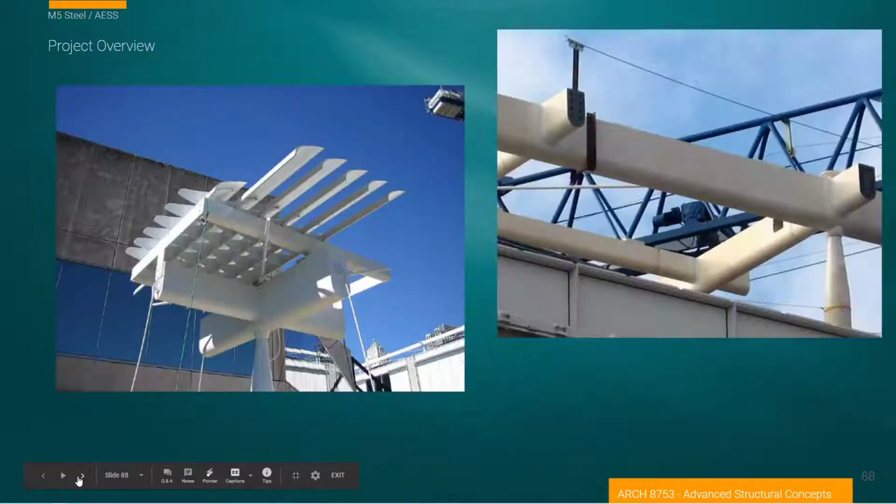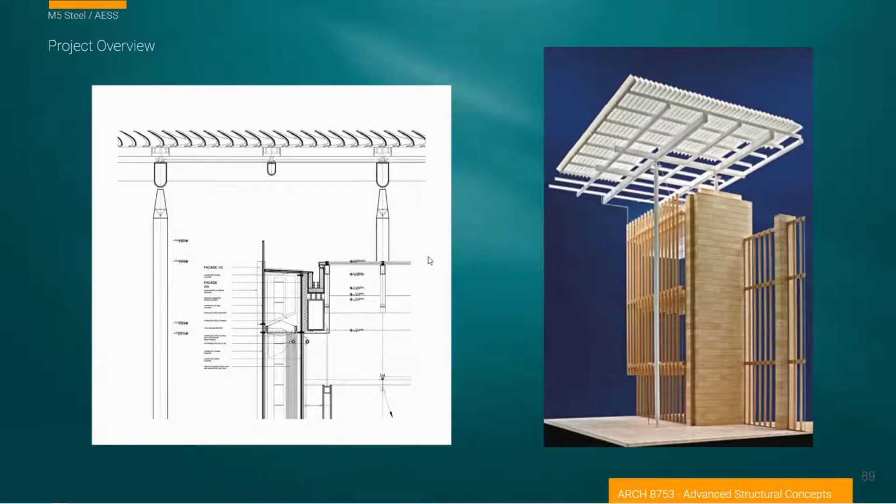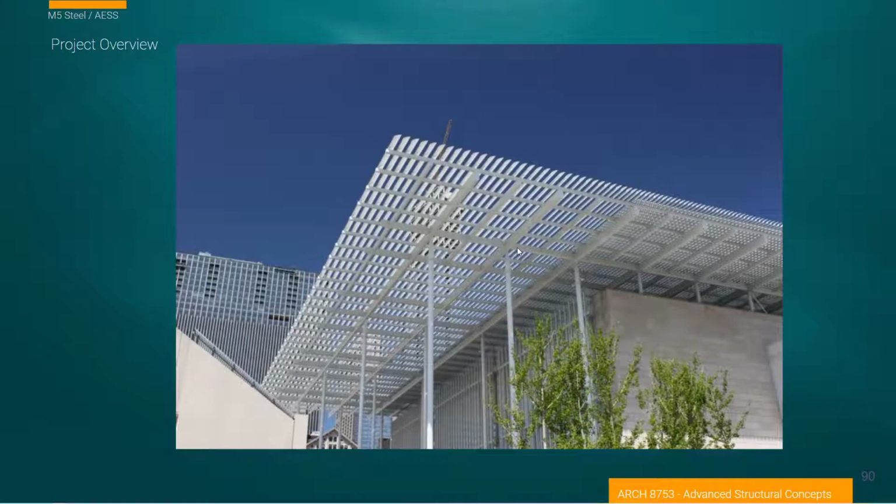I did a little bit of research through the construction drawings to get some details, so you can see this idea of the sections of the steel on this roof superstructure, the louver system. We're going to build a lot of these. We're going to make the column, we're going to make the beam elements, and we're going to make this gridded system that fits into it. Another nice detail of this. And we're concerned with the kind of loads, looking at this as a beam load, looking at this as a column load, trying to figure out the tributary areas that are being carried down through that system.